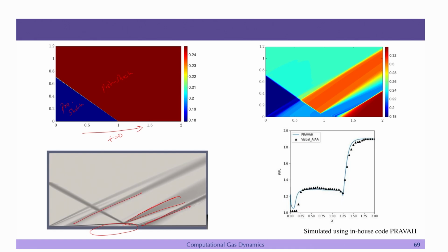This is another shock that we talked about. This is the inlet shock, because we have not used any region before this. Typically a slip line or slip region is used here, and the domain is extended, so that you do not see this inlet shock, or you want to avoid it. The solution first gets developed there and does not see the point abruptly. Right now I am just putting M equal to 2, it is like a plug flow. So, at M equal to 2 you see this discontinuity, and because of that this inlet shock gets developed.